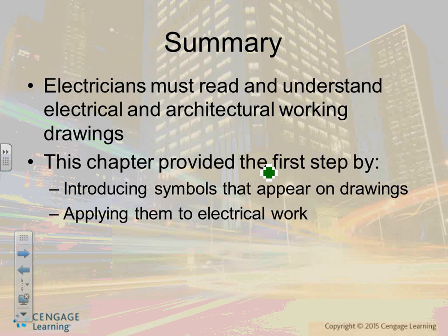Right underneath it, dashed line, conduit concealed in or under a floor slab. These are the symbols, guys, that they use for conduits. I'm not going to read all of them. The last one says UCD, underground flat conductor cable, FCC wiring system data. So that's the symbols that we use. You don't have to memorize all these. Typically, they are in the symbols I gave you guys. So just be aware, if you see an electrical symbol, make sure you go check what they refer to.